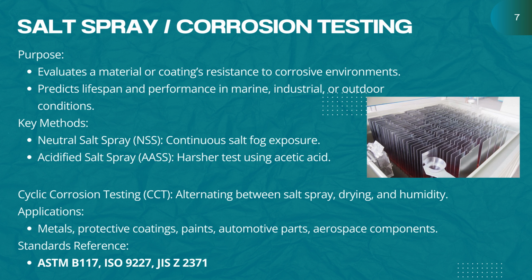There's also cyclic corrosion testing, which is more realistic. It alternates between salt spray, drying, and humidity, just like real weather cycles. This testing is especially important for metals, protective coatings, paints, automotive parts, and aerospace components, anywhere durability against rust and corrosion is critical.